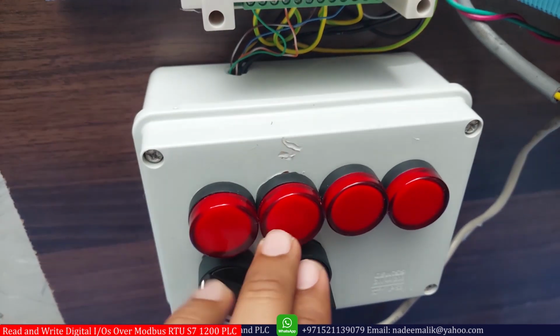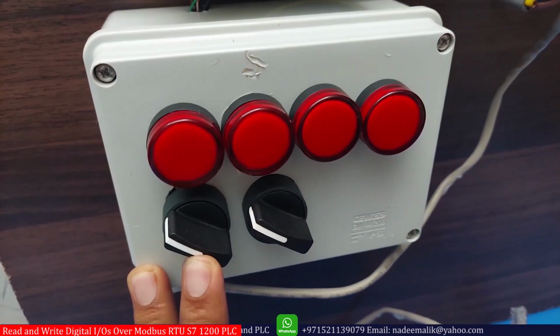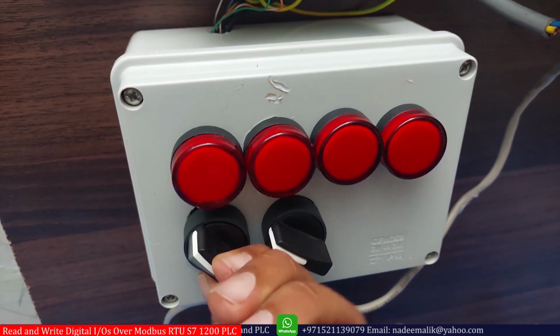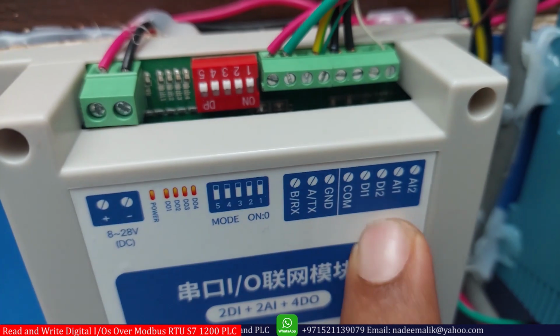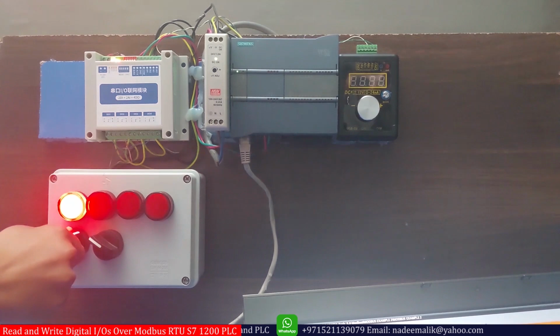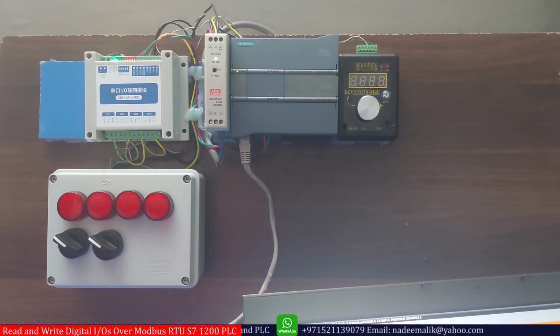We have connected some LEDs at the digital relay outputs of this module. We have connected two selector switches at the input of this extension IO module. We will program the S7-1200 PLC using the TIA Portal software to read the status of these selector switches and turn on or off these LED lights.